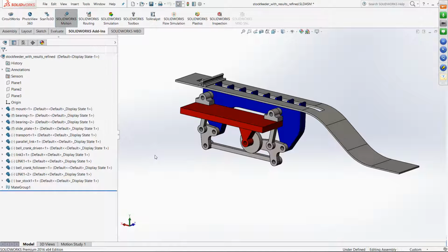Obviously questions would be, or the problems or the changes that will come into picture. Typically you do such a setup, you'll observe that the part will not move the way you want it to move. So obviously you can change the dimensional details. You can design the bearing dimensions based on the forces that are coming at that particular location. Typically for FEA, one of the important challenges will be to find the forces at those different locations.